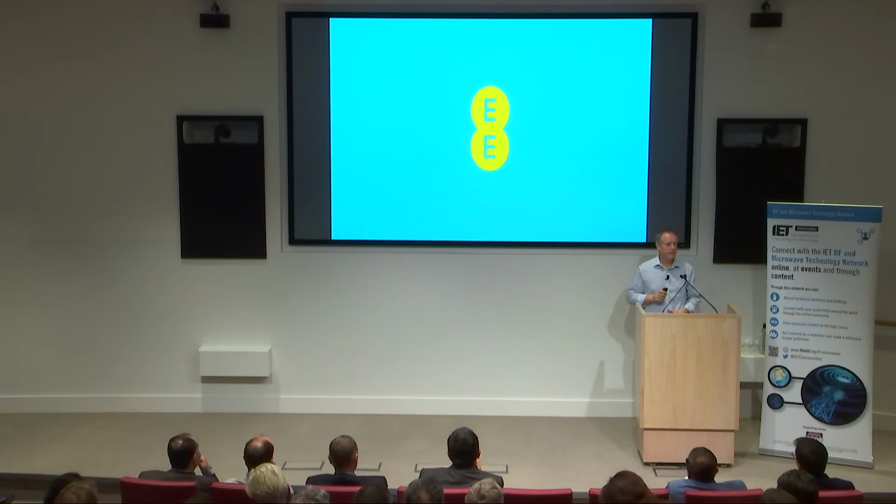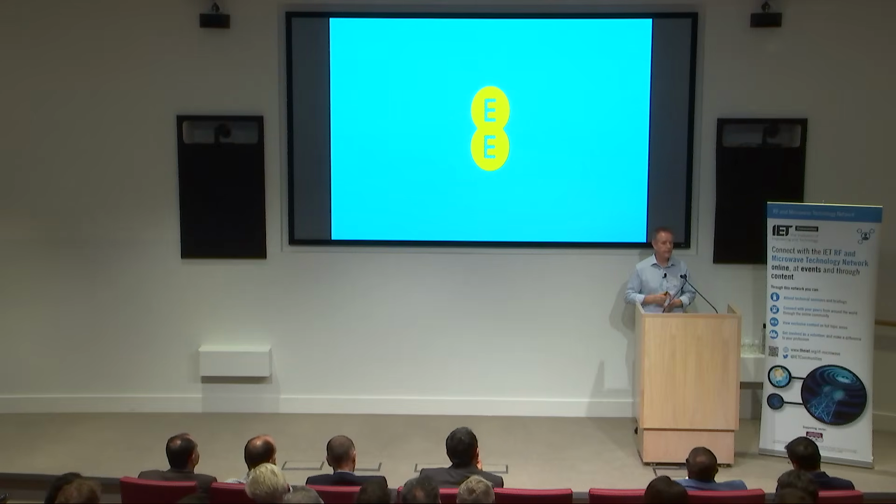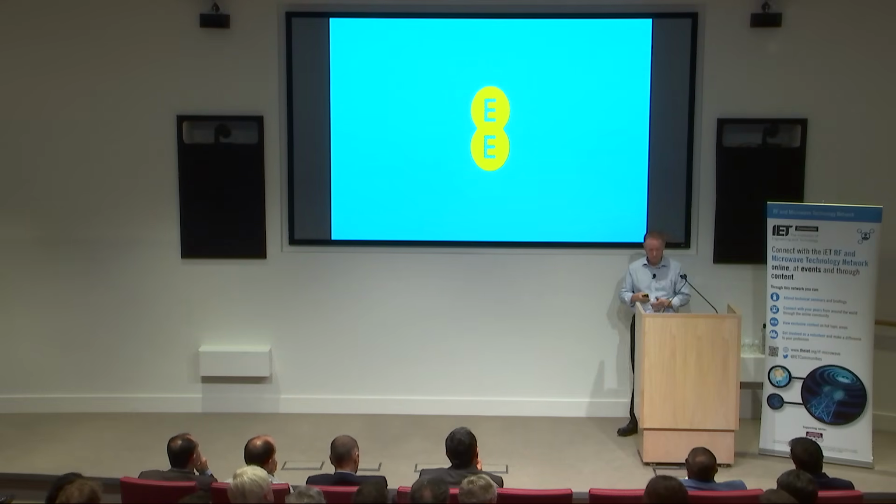Okay, so in that particular demonstration, we used 100 megahertz of spectrum. We used a 7:1 downlink to uplink ratio on that TDD configuration, 64T, 64R for the base station, and the actual UE was 4T8R. That's the configuration sitting behind what you've just seen there.